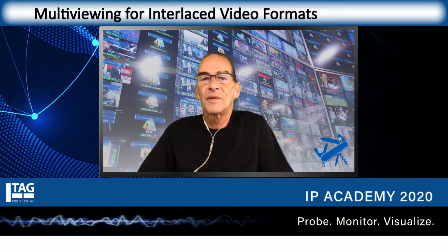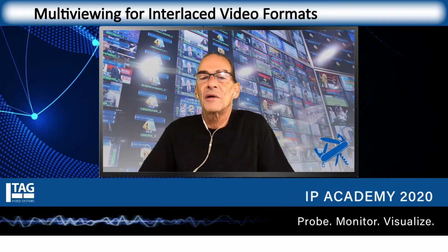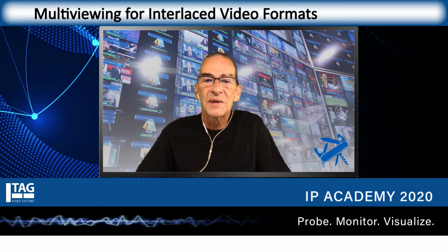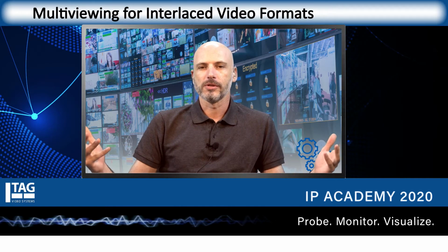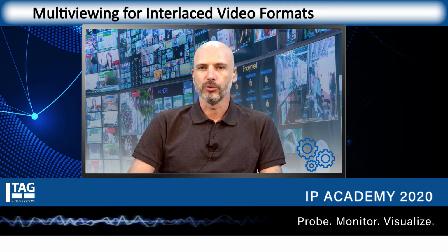So coming back to monitoring then, can we just go over the best practices for multi-viewing of interlaced content in either a progressive or a mixed production environment? I think what I've got so far from this is, first of all, we want to convert everything into progressive inside the multiviewer. Is that right? Of course, you don't have control of your sources. If your sources are interlaced, this is what you will push to the multiviewer. You will not want to convert it externally before pushing it to the multiviewer because it's additional equipment and additional points of failure where you don't really know what might happen.